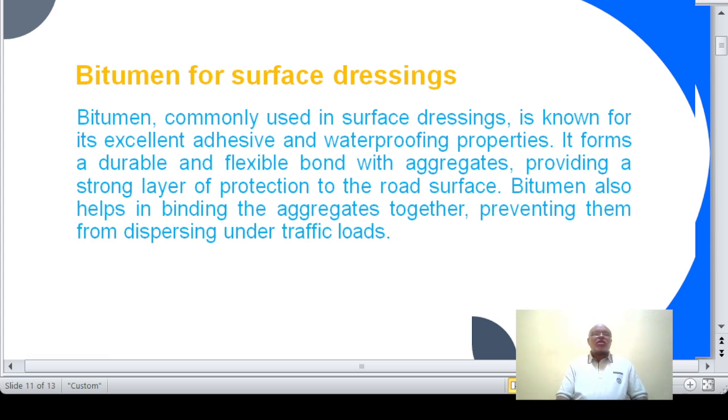They should wet and adhere to the chips at road temperature, and they should be strong enough to resist traffic forces and hold the chippings at the highest prevailing ambient temperature, and remain flexible at the lowest ambient temperature, neither cracking nor becoming brittle enough to allow traffic to pick up the chippings. And also, they should resist premature weathering and hardening.